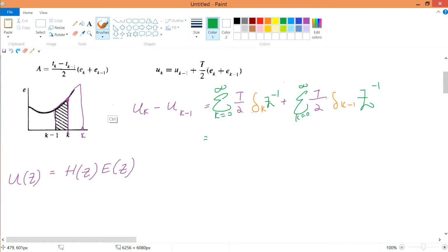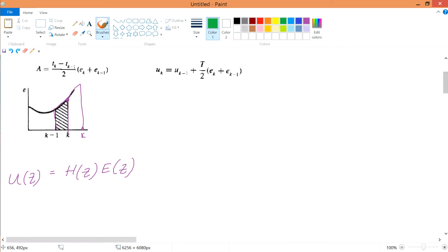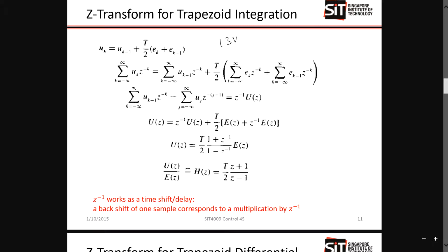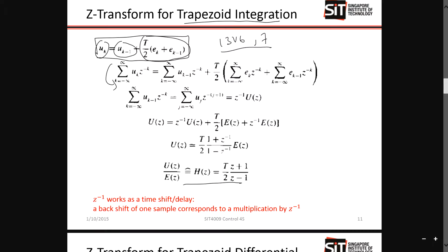In this manner we're going to prove certain things such that it'll be clear in terms of BIBO stability. Hopefully this is pretty clear. Remember back to our lecture 4 videos, I think, where we touched on trapezoidal integration and changing it into a transfer function. This is the part where we input your previous output, plus your trapezoidal input, in order to get your current output, and then we rearrange a few things.